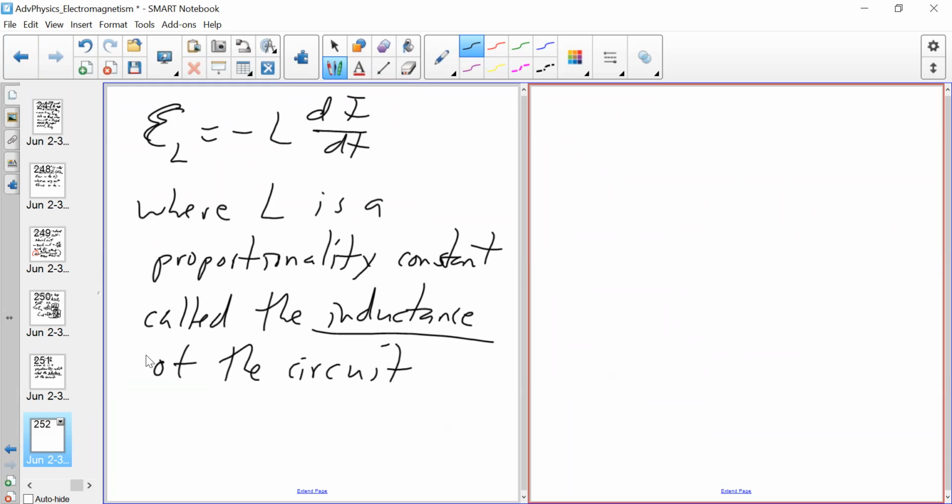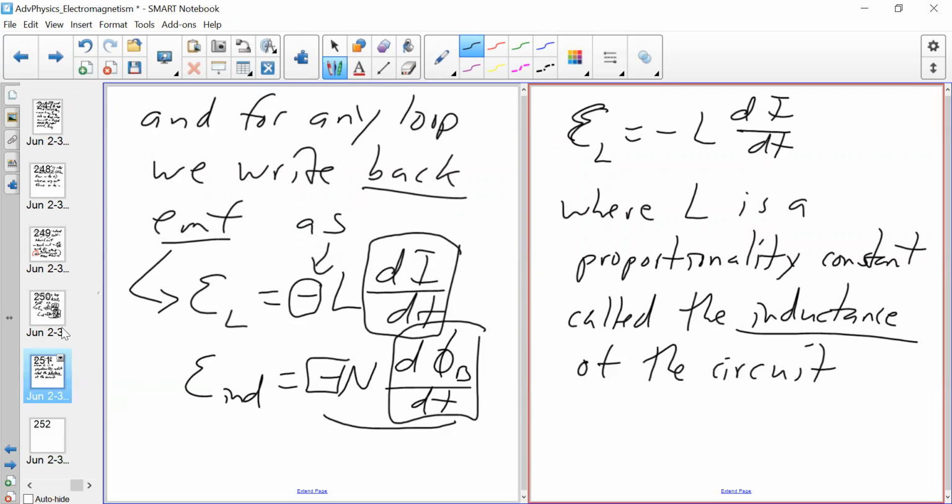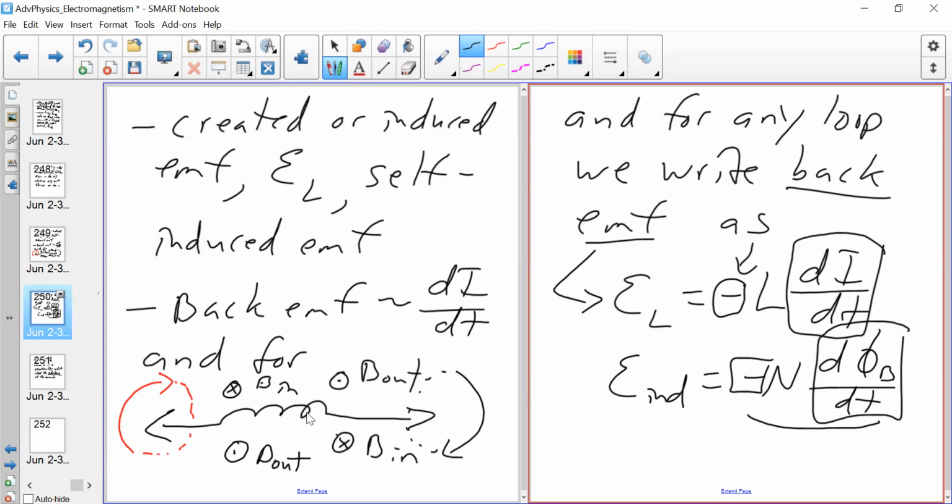All right. So let's say that we had a part of the wire, part of the circuit before. I was showing that we could have a part of this circuit with a wire coiling around one part of the circuit. If you do have this, there's going to be current going through the coil, and it's going to produce its own magnetic field. And as the current is changing, it produces a new magnetic field that goes the opposite direction, which creates a new current. And we call this device an inductor.